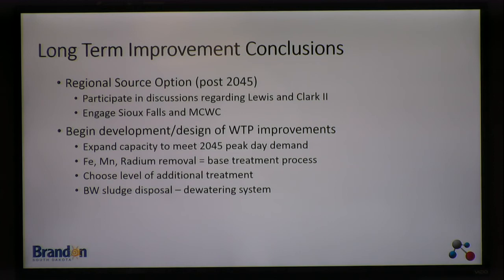Nitrate levels in the Big Sioux have proven to be increasing as well, right? They're not going away. The data are limited in terms of places other than the Brandon wells. But in the Brandon wells you absolutely have Well 1 that is contaminated, in the range of 5 to 10. I think it's at 7 or 6 right now, right? But really that's a function of the recharge area, where that water's coming from. So really that's the history. It's a recognized thing, if you have RO available or if you have blending available.